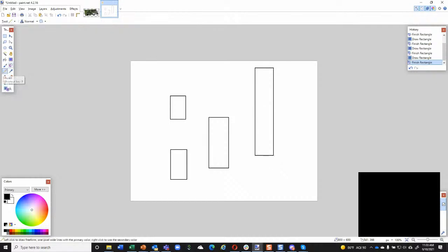I'll just do the pencil real quick. So these would be something like LS93s. I forget the actual part number for a magnitude comparator. I want to say it's an 86, but I think that's just an XOR gate, which you can kind of do the same thing with. 86 is an exclusive OR gate. So it's probably something like an 85 or around there. I forget what it is, so I'll put a question mark.